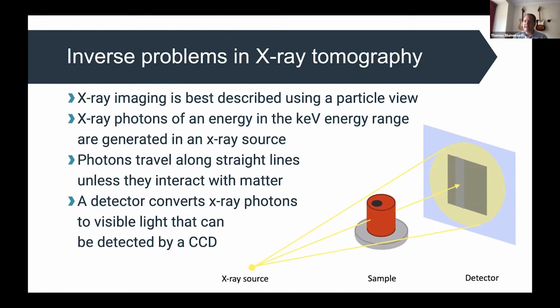And we're detecting how many we're getting through the object. We do that trillions of times with trillions of different X-rays, and we then rotate the object and look at the object in different ways. And we've seen this morning, there are lots of examples out there, and if you have a nice sample where we can shine lots of X-rays through and we get lots of data and we reconstruct the image, we get really good volumetric images.